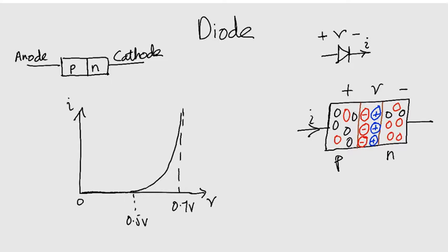Typical measured V-I characteristics for a silicon diode are on your screen. The current appears to be 0 until the diode voltage is almost 0.5 volts, at which point the characteristic starts to rise. This apparent knee is entirely due to the mathematical behavior of exponentials rather than some physically related threshold in the device. Nonetheless, on the scale of milliamperes, silicon diodes appear to have a threshold voltage of 0.7 volts.